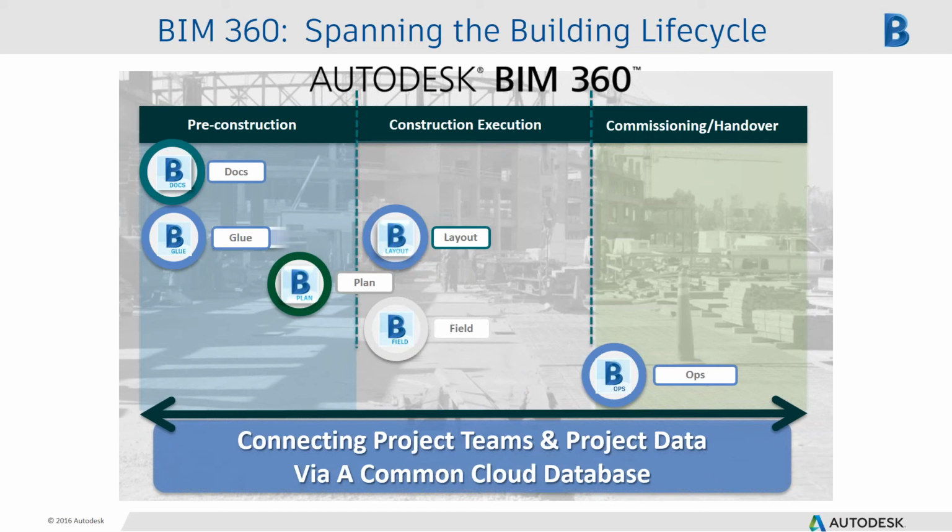The first tool that I like to talk about is BIM 360 Glue. That's going to be the pre-construction coordination of the models, identifying any clashes between those models, and sorting out any potential issues that you might have pre-construction, as well as into construction execution. So as we're executing on that model, building that out, continually updating the models and running those clash coordination meetings to determine that there's not going to be any major issues on the job site.